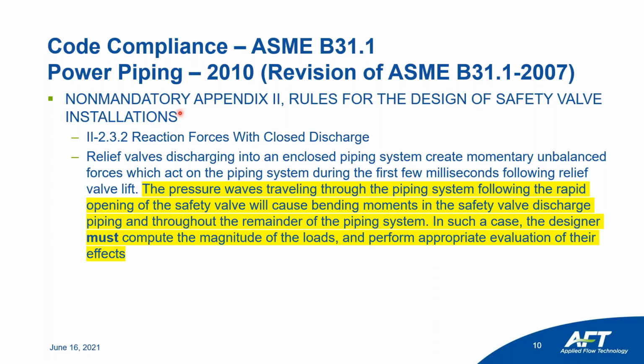So that's why we're not going to touch them, but still you can use xStream to calculate those reaction forces when a relief valve discharges to the atmosphere. So we'll be addressing, with the example, section 2-2.3.2, reaction forces with a closed discharge system.